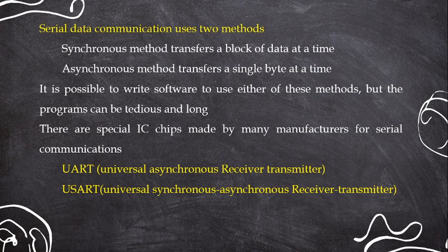And it's not sufficient that you have the program written, you also need to have the hardware which supports that operation. And hence, there are two chips, UART as well as USART. UART stands for Universal Asynchronous Receiver and Transmitter, while USART stands for Universal Synchronous as well as Asynchronous Receiver and Transmitter. In this session, we will be looking into the Universal Asynchronous Receiver and Transmitter. This is the mode of serial communication which is supported by the 8051 microcontroller.